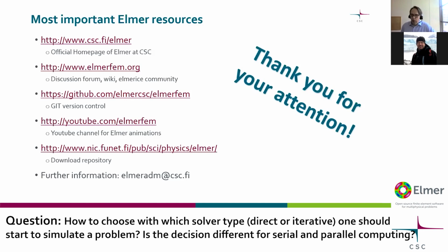So of course, if you go from a small problem to quite a large problem, then you will really feel that. In 2D, this is not so dramatic because the bandwidth in 2D tends to be smaller. So I would say that in 2D, the scaling law is easily 1.5, and then it's easier to compete with the iterative solver.